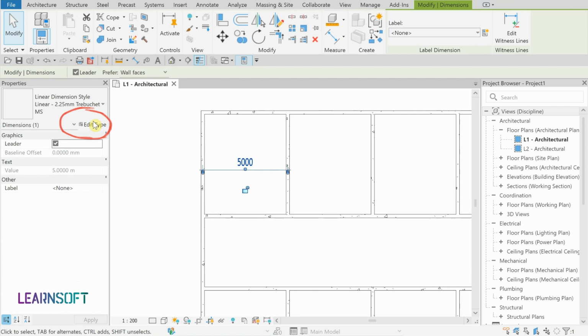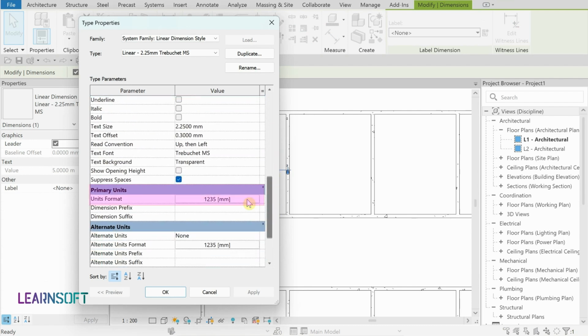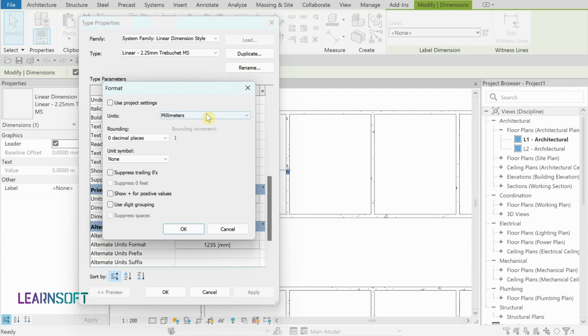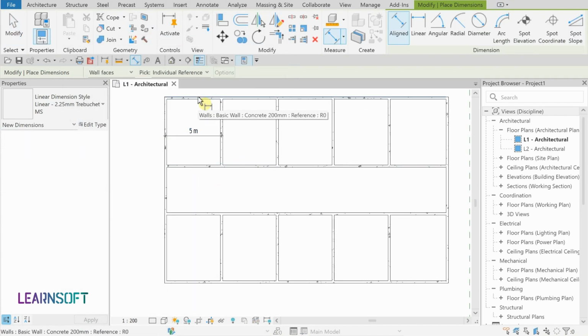As a review, select the Annotation and go to Edit Type. Find Unit Format. Change related parameters to the meter-based measurement system. For precise drawing, I select 2 decimal places and tick Suppress Trailing Zeros for showing zeros. The annotation shows that the same values for offsetting distance are applied.